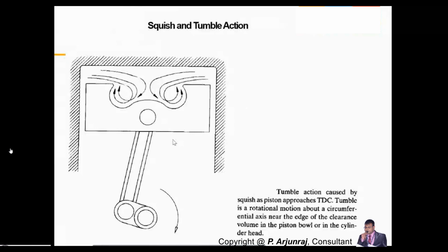squeeze. And you also have one more term called reverse squeeze, okay, which will help to spread the flame during the later stage of combustion. I told you the flame front or the flame distance should be lesser, so you get a better performance. So you need to avoid the reverse squeeze. Squeeze is always good, where you're allowing the radial movement of the gas